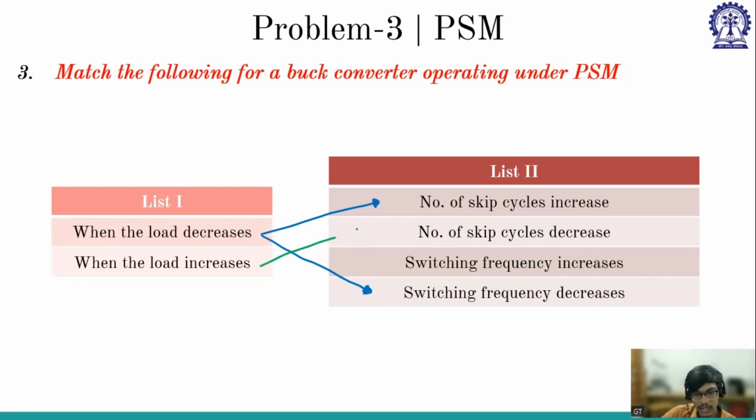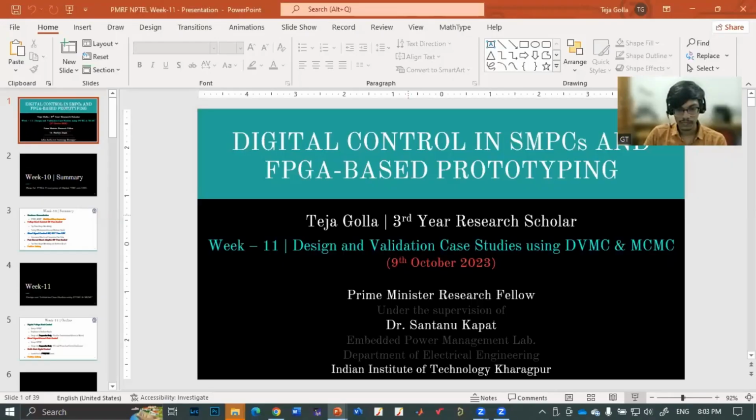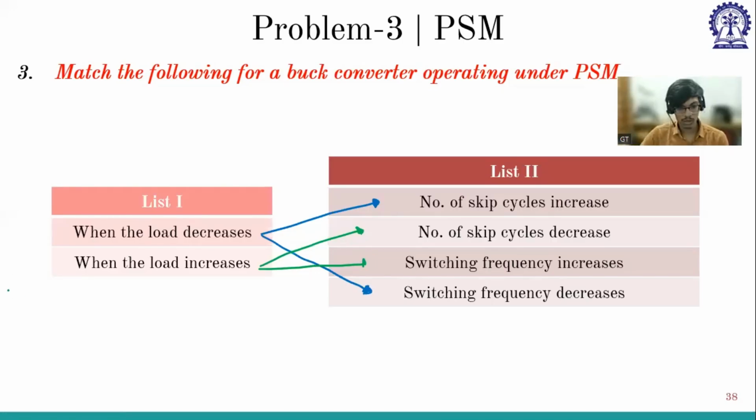Skip cycle decreases and frequency. Yes. So when the load increases, the skip cycles decrease, so the switching frequency increases. Again, this is in slide 32. If you have any questions, you can refer to this slide.